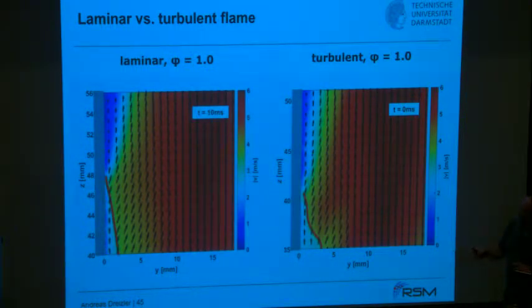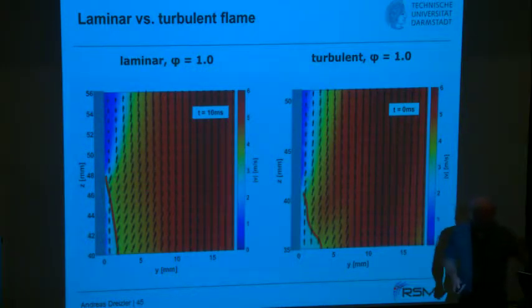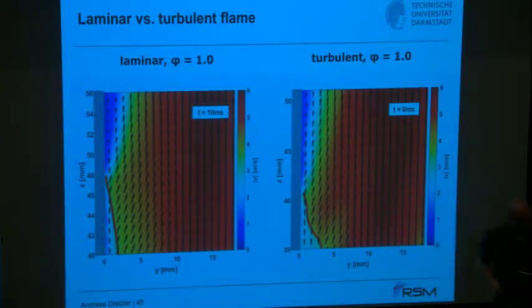Although it's laminar, there is a remaining frequency that is measured not only here at the flame tip, but also at the nozzle exit. That is due to this bottle-like shape that creates low frequencies. And this gives rise to a remaining fluctuation of at best maybe plus or minus 150 microns. So unfortunately, whenever you do experiments with point techniques, 150 microns matters, and you need to know where the flame front instantaneously was. That means the COT measurements in the end needed to be done simultaneously with flame front tracking.